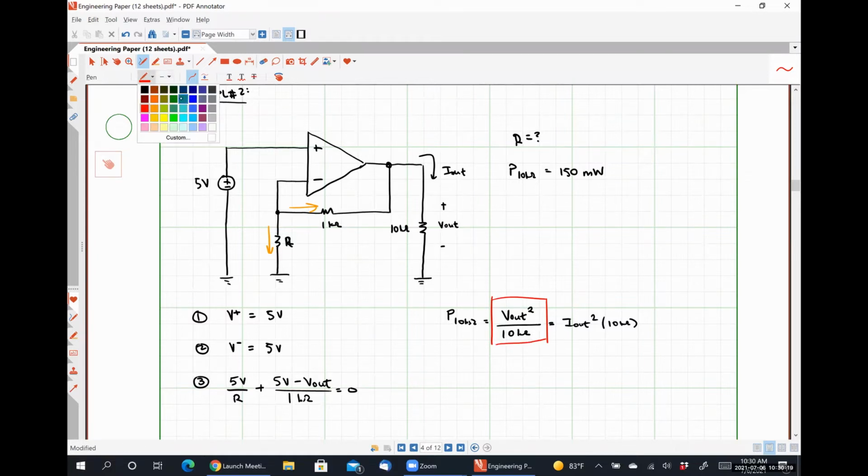As a matter of fact, we will literally never use this relationship, and it's because we don't know how the current that is being output by the op amp behaves without knowing what the voltage present at the output is.